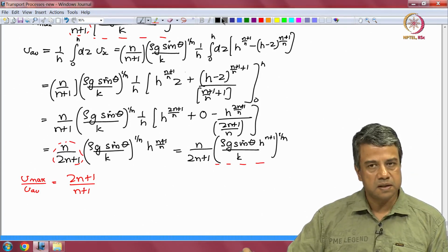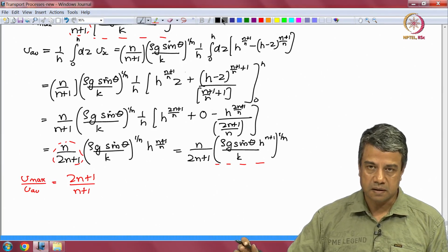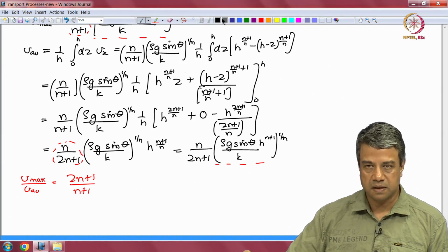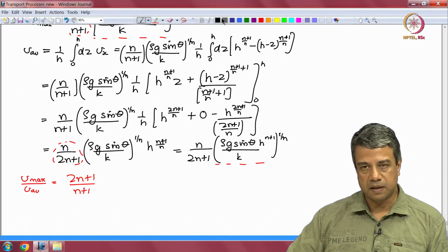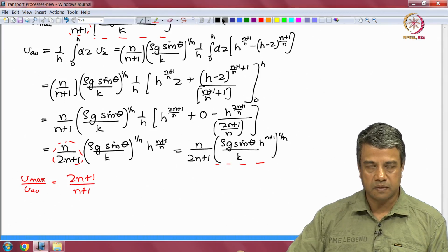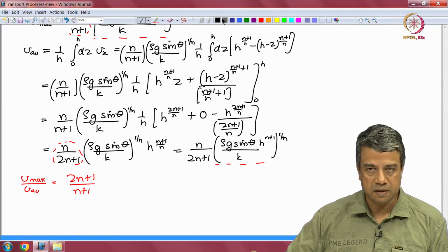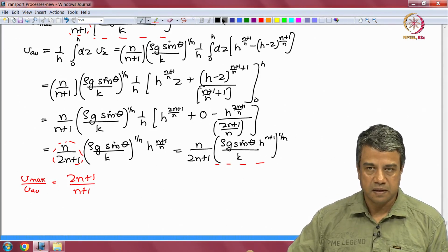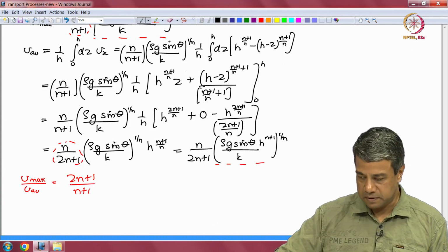So, this is how we consider problems where the source density is a constant. The relationship between the flux and the gradient could be linear or could not be linear. In either case, since the source is a constant, the force density or the mass production rate per unit volume or the energy production rate per unit volume, if that is a constant, the flux is a linear function, and then you use the relationship between the flux and the gradient in order to find out what the profile is.